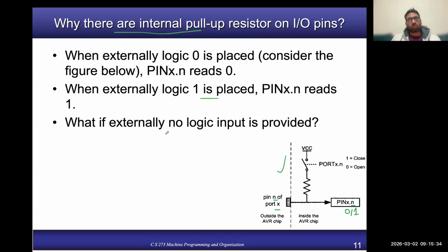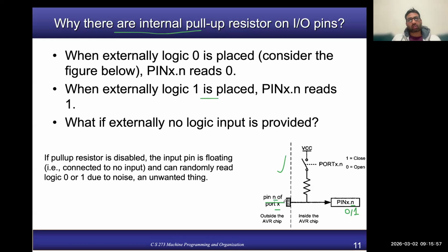However, what will be read in the pin register when we don't place any value on the external logic, let's say you have not connected anything to this pin, which means you are not driving any signal? That is a problematic situation. If the switch is not closed, it is open, which means the pull-up resistor is not enabled, the input pin will be floating, that is, connected to no input.